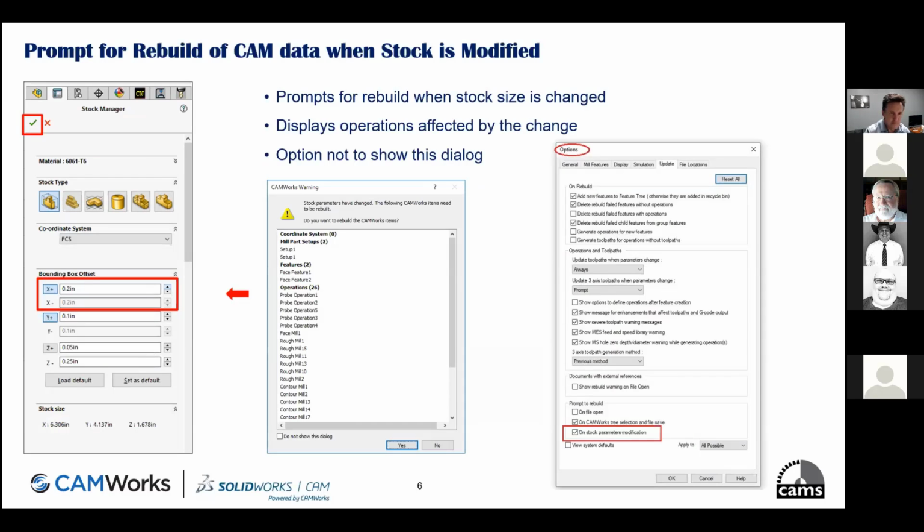But yeah, what happens is a lot of times people will program a part and they'll come up and be like, oh, I couldn't get that size stock in. I had to change, now I have to change my stock shape. So they'd have the part already programmed, and then they would change the stock, and sometimes they would forget to go back and adjust some of the features according to the new stock definition. And if they miss one feature or something, you could have a crash or something.